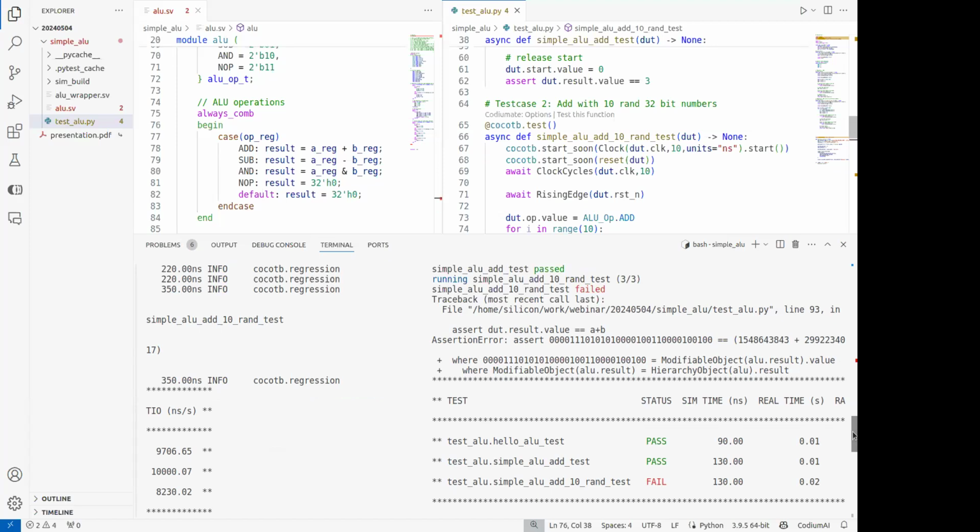Okay, so it seems something overflow. Whenever it generates the different numbers, what is actually happening here? It has some overflow. I mean, not overflow exactly, it has a carry. These two big numbers were added, and it was expecting some carry, which, if you took 33 bits, maybe the result would be matching. But since we are truncating to a 32-bit result, maybe it has some overflow.